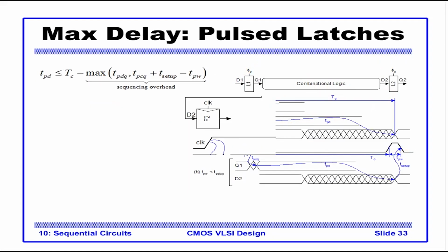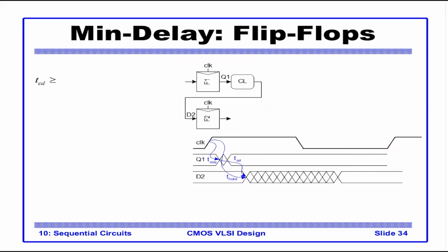So now the minimum delay of a clock, now in this case we will take TCQ. So the Q1 changes after TCQ, D2 changes after the minimum delay of combination logic, which is the TCD in this case. So now TCD plus TCQ should be such that they do. So this clock is actually the clock reaching flip-flop 2, F2. The delay change at D2 should happen such that it meets the hold time requirement of this clock.